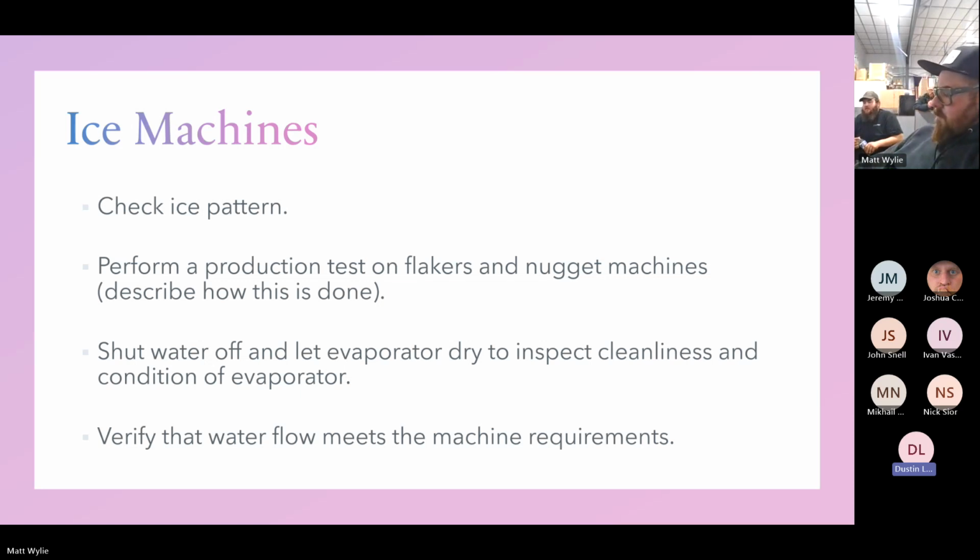So 1/2 inch to a plumber is going to be 5/8 in refrigeration piping. Based off whatever vendor you're at, if it is copper and you need a fitting, like Matt said, if you go to RSD and get a 1/2 inch fitting, it's going to be too small. So just keep in mind the difference between water line and plumbing measurements, and refrigeration piping measurements.